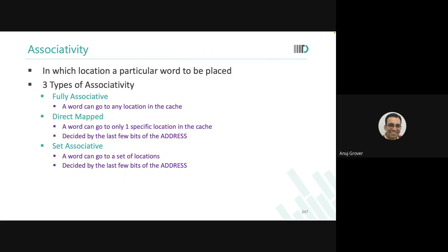Now there are just two things. One activity it is doing is comparison. The other activity is the communication protocol. I know it's not a general purpose processor. It's not a processor that I'm going to load in a hugely big way. And just two ways could be sufficient, or even a direct map cache could be sufficient. But when you're talking about very high performance processors, tightly coupled, fully associative caches are used.